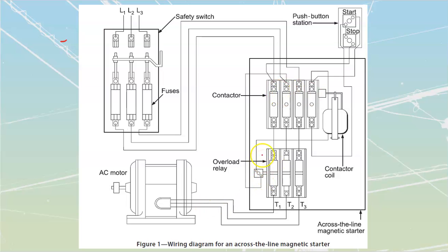When it comes to my actual connections inside of here as well, all of my control connections are done the same way. I can follow a line from here. I can see that I've got, hold on, look at that, 3 wires. Just circle that over there. 3 wires going up to my stop-start station. What type of control is this? You should be familiar with this, that we call this 3-wire control, because we only need to bring 3 wires up to that stop-start station over there.